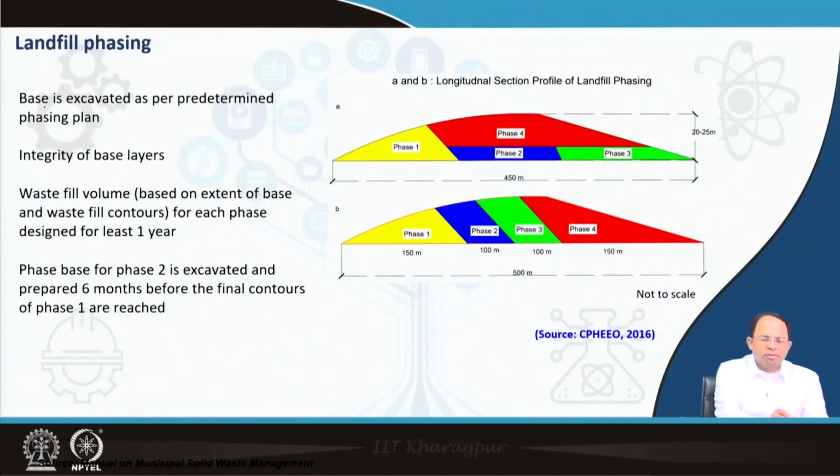We have discussed that the base is excavated as per the predetermined phasing plan. So we have to discuss the phasing of that particular landfill site, and accordingly the base has to be prepared. Because these phases are not done simultaneously but one after another, at the end of the day the bases have to be integrated so that there is no leakage between these two bases, right? Because of the two phases, we have bases constructed at two different time periods, so there may be some gaps in between. That should be prevented, so the integrity of the base layer should be maintained.